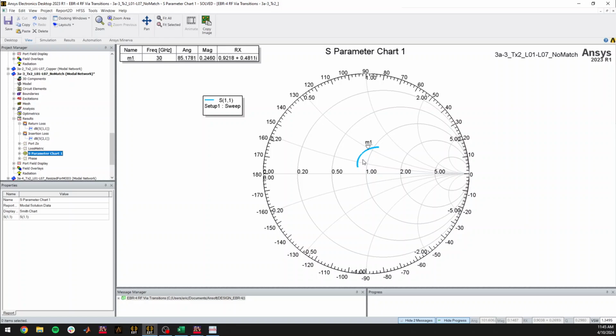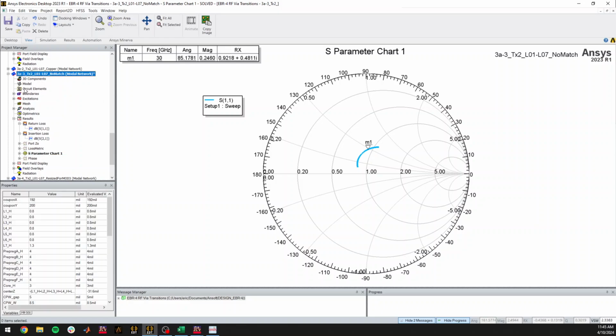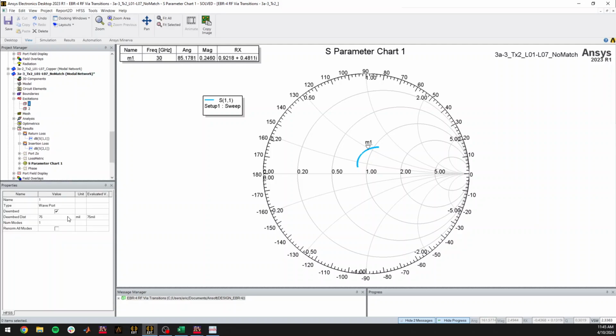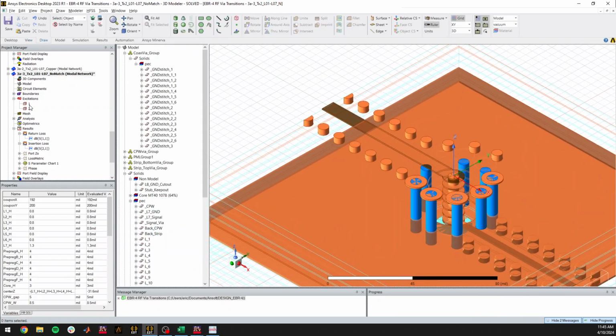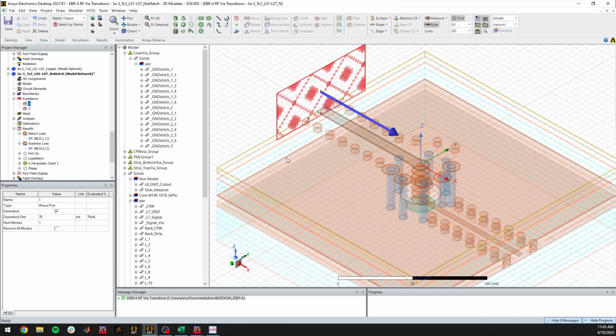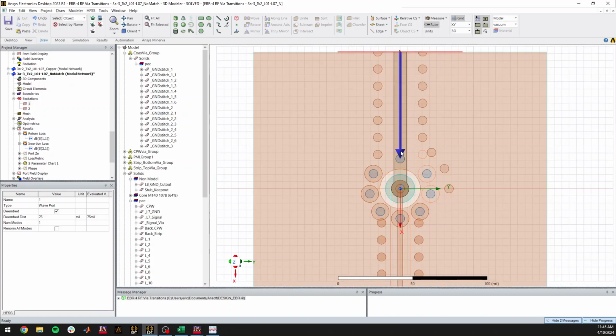And it's looking at it from the perspective of the CPW line. So we would like to improve the performance here, and the way you can do that is some sort of matching network, of course. One knob here, a kind of trick that you can use in HFSS, is to change the de-embedding distance of your port. So I can show it better here. If we have a port right here, we can de-embed this port by some length to see what the impedance looks like at that de-embedded plane.